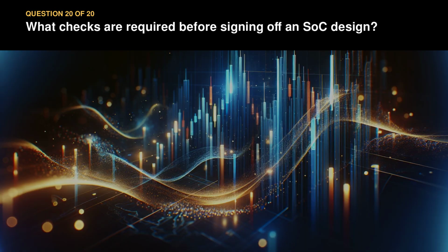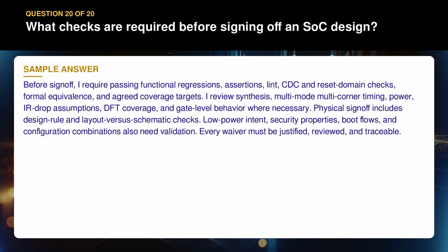Question 20. What checks are required before signing off an SoC design? Before sign-off, I require passing functional regressions, assertions, lint, CDC and reset domain checks, formal equivalence, and agreed coverage targets.